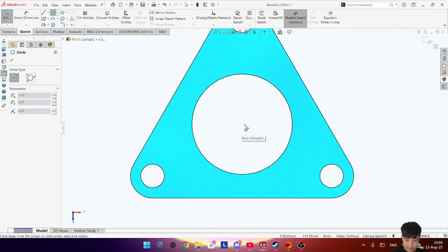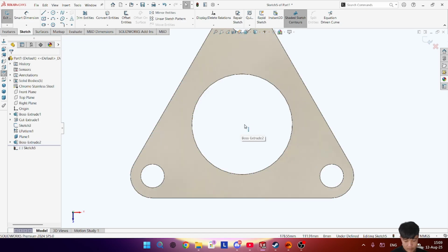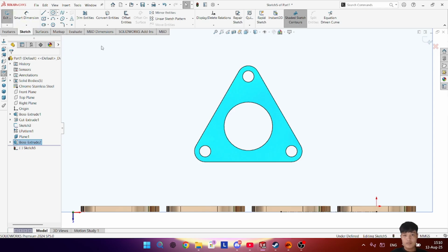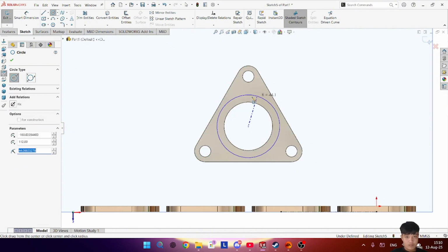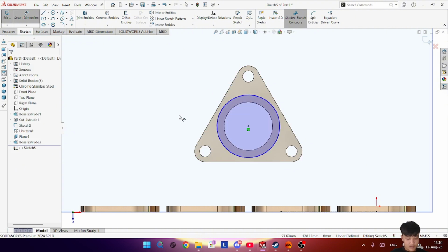Define sketch circle. We want to connect first this two one. So how we will do this one? Let me choose this one. Sketch circle. Select this and find out this origin point and define this diameter 70 millimeter. Now exit.